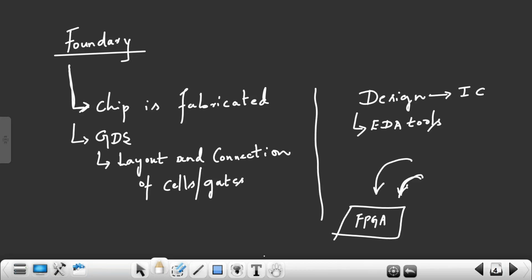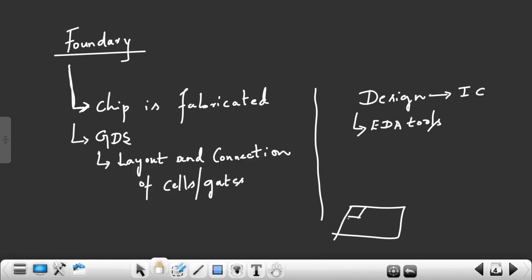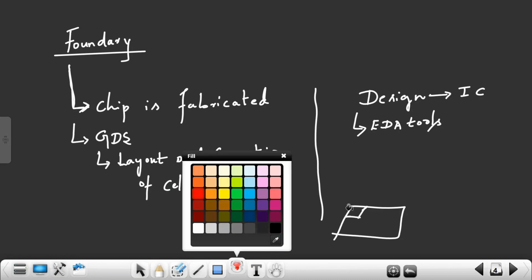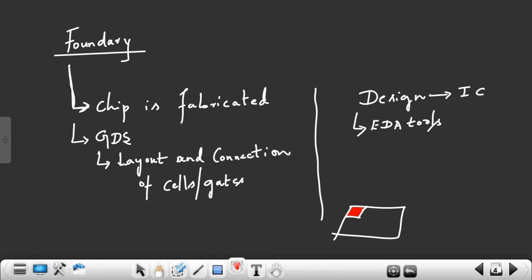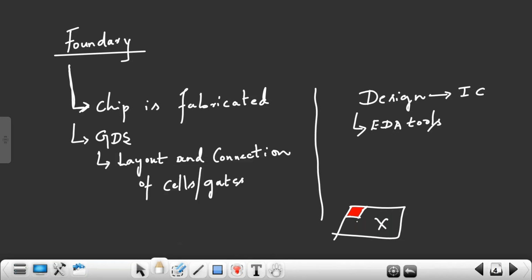Good. Right? I don't have control over the FPGA, right? For example, I have a D flip-flop program. My D flip-flop program is taking only this much area. Entire this area is wasted. For that reason, I cannot cut my FPGA. I don't have control over the design. Already cells are present inside the FPGA. I cannot change internal cells. I am only responsible for connections between the cells. So the designer doesn't have flexibility over the design.